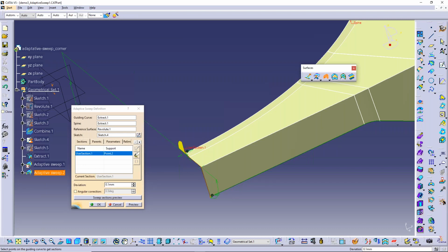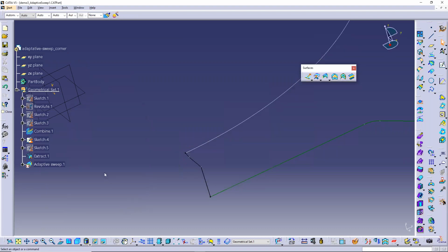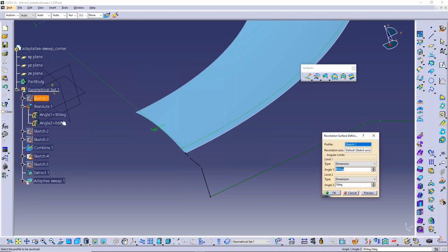It's not a need for what I did here, but it is what I did because of experience, creating an extract curve from that surface there that I just double clicked on, and using the extract, which is a parent element, obviously. The surface itself is a parent element to the extract, but the extract is independent in the sense of selection. It's its own feature there in the tree.